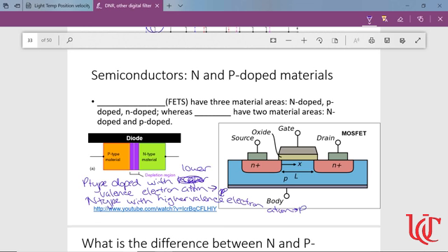What had a lower valence electron than silicon? So silicon had 4. I'm looking for one that had 3. That was boron. Okay, so boron made our P-type materials. Phosphorus made our N-type materials. It's called N-type because, again, with that extra valence electron, it's like I have a negative charge that can move. Okay, so hence a negative charge type. With a P-type material, it's called P-type because boron only has 3 electrons. Therefore, it has a hole where it would like another space to share with its neighbors covalently. So it's like that hole is the absence of an electron or it's a positive charge.